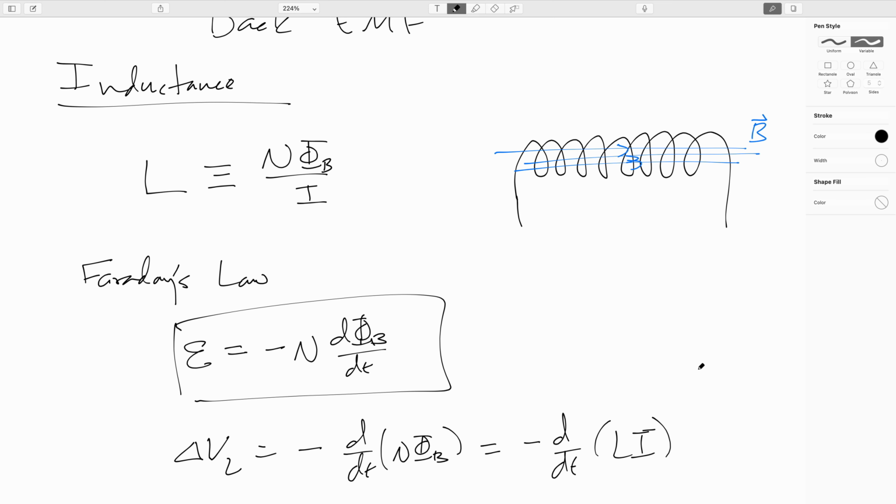Now, as a little tidbit here, you will notice that as the current flows through the inductor, and it's interacting with its magnetic field, there will be a magnetic force. And if you play with the right hand rule, you can convince yourself that this is going to try to collapse it down a little bit. There will be some twisting action happening. This is why light bulbs, for instance, have their filaments coiled up. It's to help absorb some of the shock in that twist.